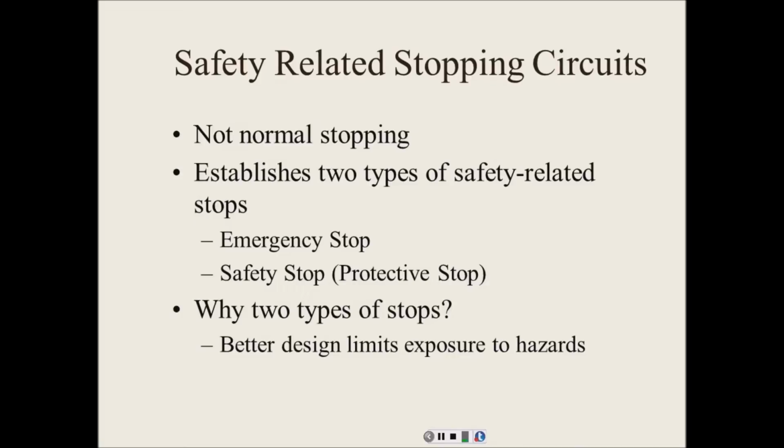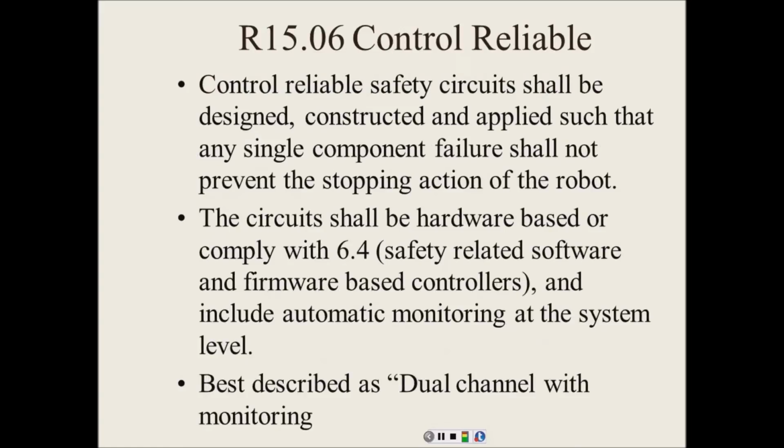So when everything was working okay, the pilot had force sensors in the yoke and the pedals, so the pilot was inputting the information into a flight control computer, and that was what was flying the plane. But if something happened to that computer, they had these disconnect panels. They could jerk up, and then they took control away from all the hydraulics, and they flew the plane by cable. So they still had the cables hooked up. So that's a redundant system, right? If something goes wrong with the other one, then the backup takes over. So that's why we need two types.